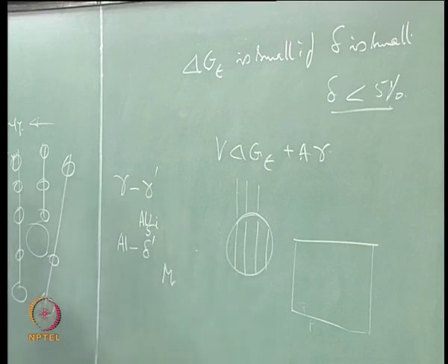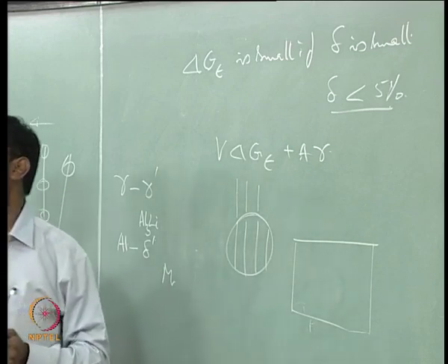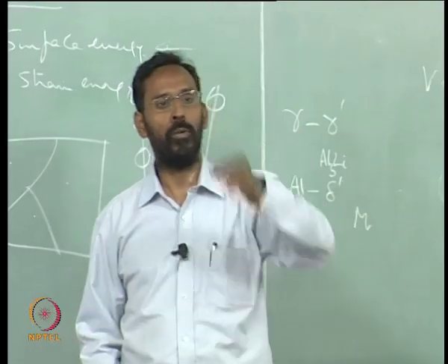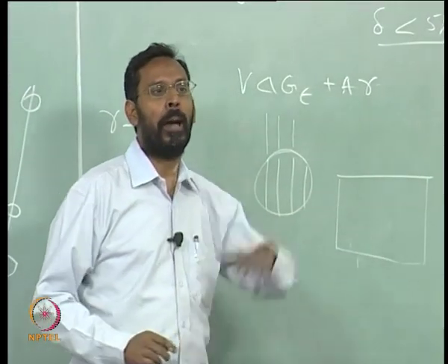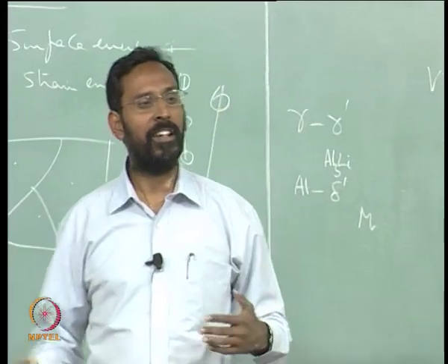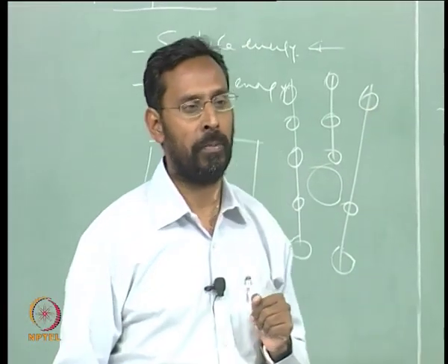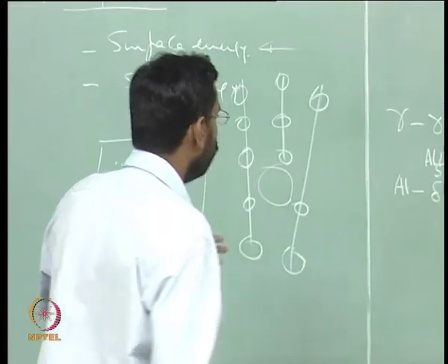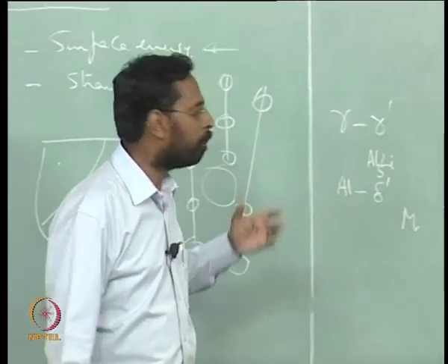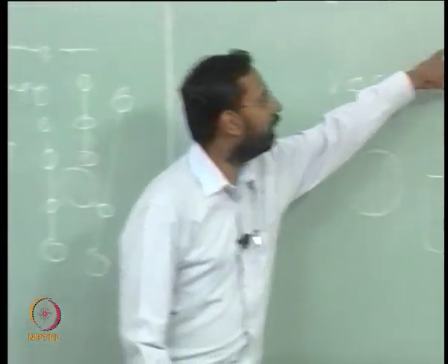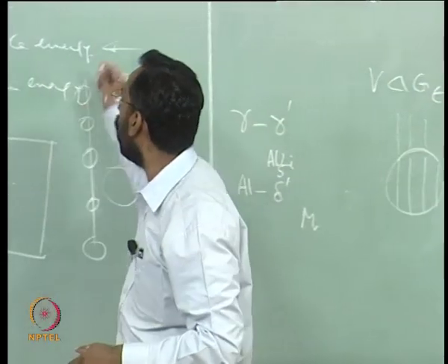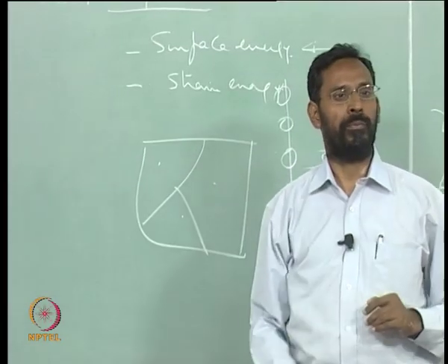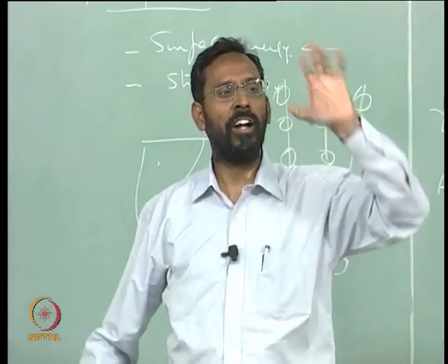So a sphere is avoided, and the other two possibilities are a plate like precipitate and a rod like precipitate, and you see that a plate like precipitate has a better compatibility, and as a result in most of the cases you see plate like precipitates, because the delta is larger. So this is all more of somehow minimizing the overall energy, but this is all at the starting only.